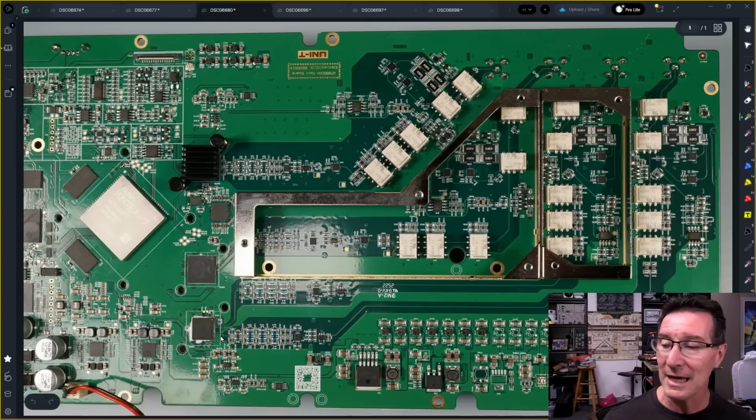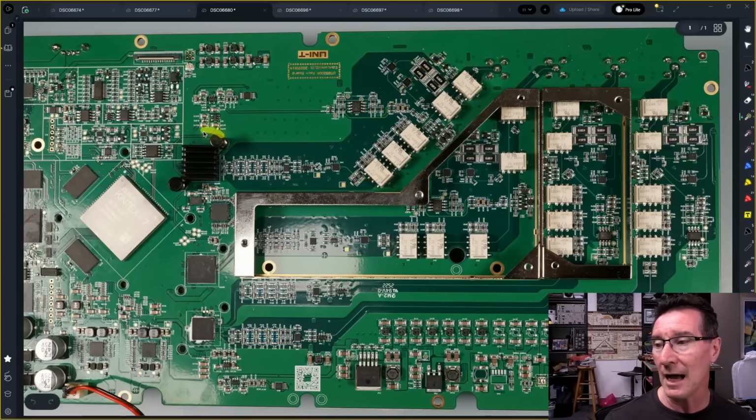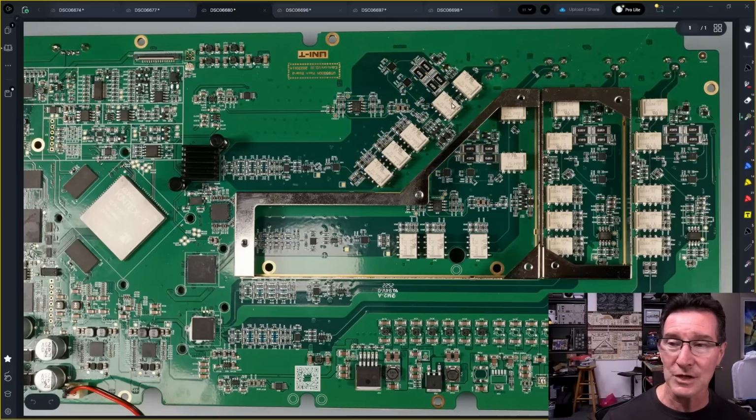And this one over here is a different DAC part again. So you can see we've got one channel here, like this, which has got one of the big 16-bit DACs, the 2.5 gig sample per second. We've got a 50 ohm output impedance. Then we've got our switching relays for different levels and stuff.